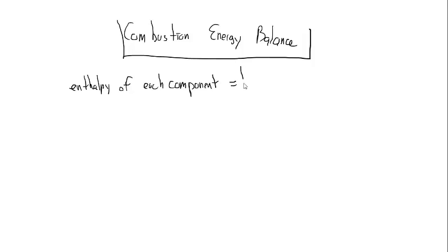It is equal to the enthalpy of formation plus the sensible enthalpy adjusted for the reference state. Again, this enthalpy is a function of temperature, and this one is a function of 25°C.